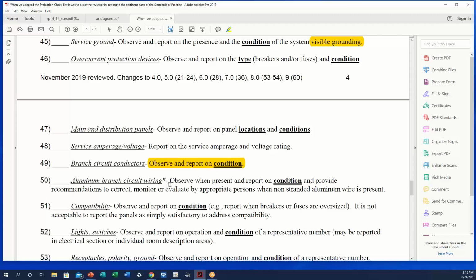It's bad. Bad. You look at the panel and it's single strand, everybody. You can see it going into the breakers. It's still bad. Write it up.